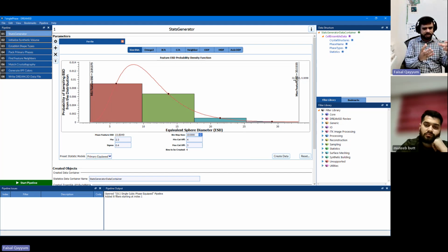If the equivalent sphere has the same volume as your grain, what will be the diameter of the sphere? So basically what it is fixing is the size of the grain. It can have a complicated shape, but what will be its size? By changing this estimated sphere diameter, we will change the grain size theoretically, right?